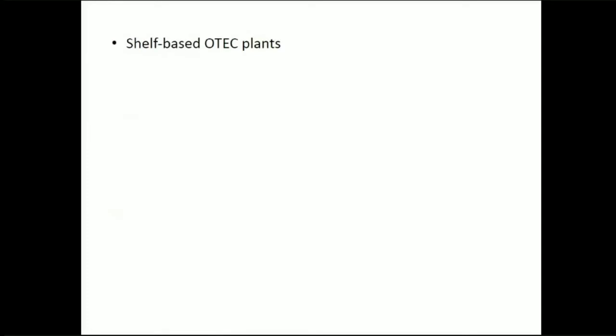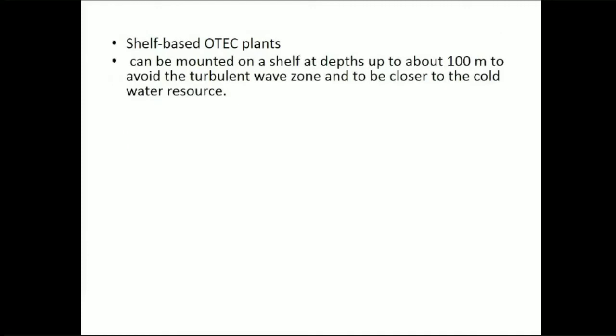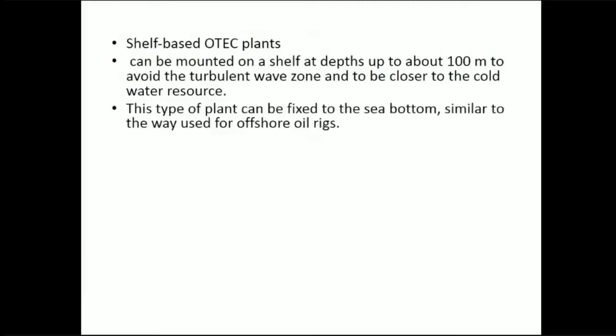Then another type of OTEC power plants are shelf-based systems. They can be mounted on a shelf at depths up to about 100 meters to avoid the turbulent wave zone and to be closer to the cold water resource. This type of plant can be fixed to the sea bottom, similar to the way used for offshore oil rigs.